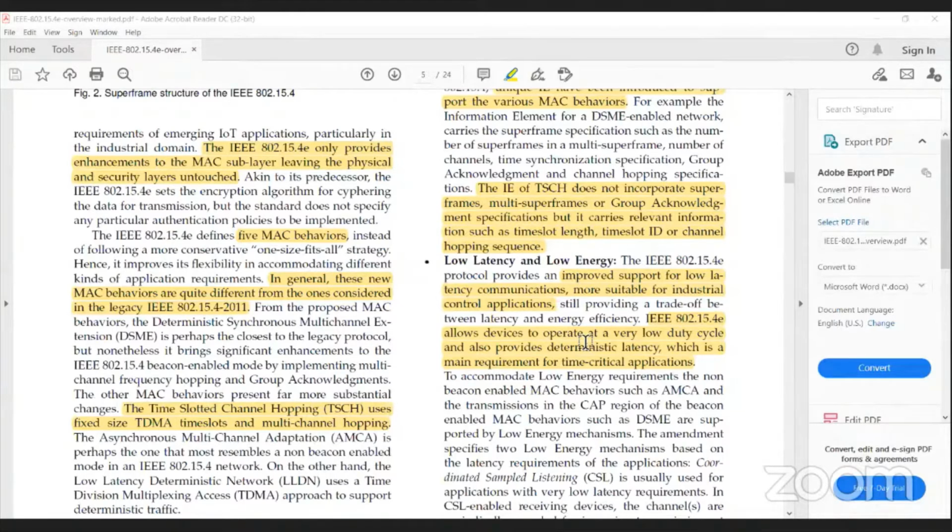But once, let us say in a steady state, all nodes have got their GTS slots, there should not be any collision. And after all, it is beacon enabled. So periodically the beacon will keep coming. And once the beacon comes, you know where your CFP, that is the contention free period, starts. Within the contention free period, you know where exactly your slot is, and there you push a transmission. Why should that be a bad idea? It's also, in a way, deterministic, right?